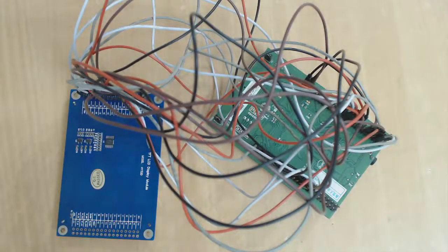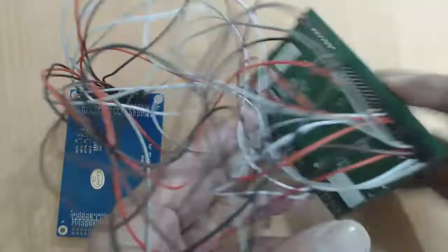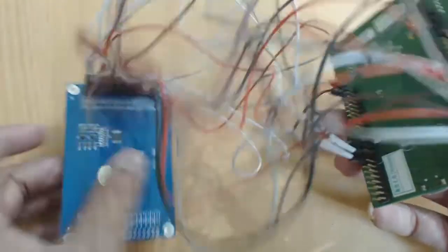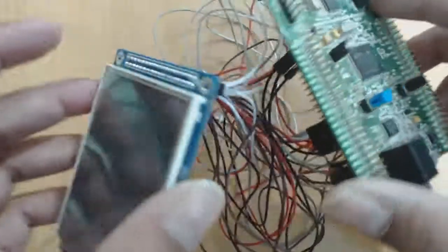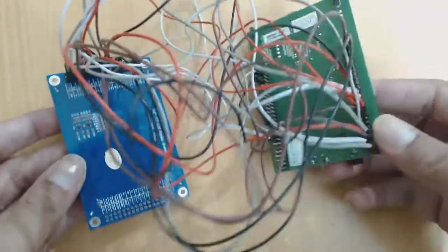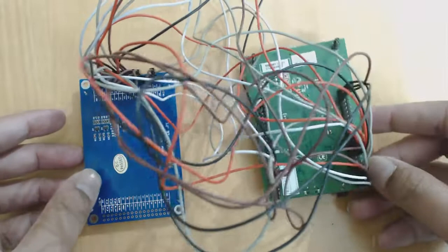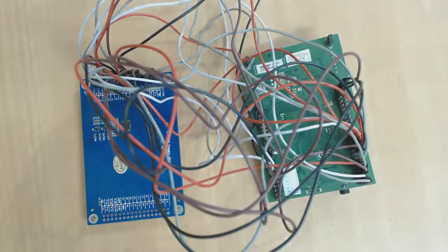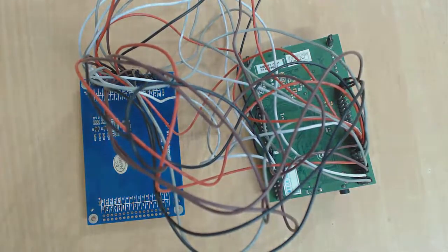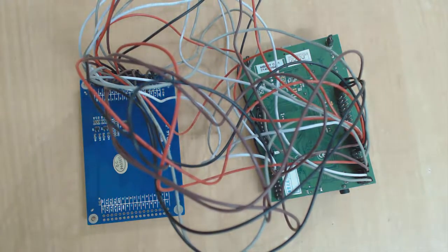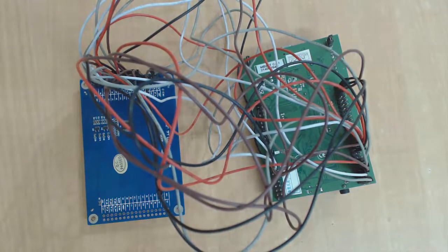Okay, so now I have connected all the wires. I have connected all the 21 pins that I have shown you on the table. And I have connected the 3-volt pins and ground pins also. Hence total 25 wires going from Discovery board to LCD module. Okay, so our circuit is built. We have properly connected the LCD to the Discovery board. Now we can start writing the code for this from the next tutorial.